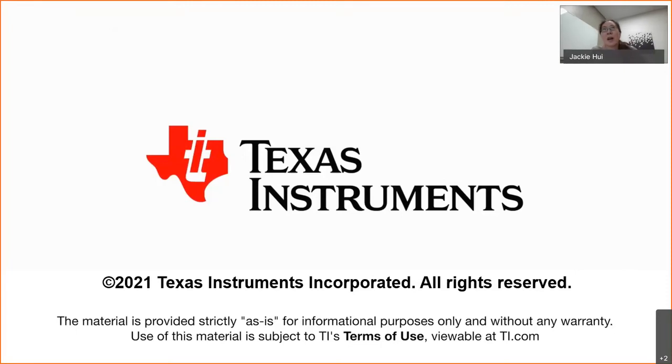Right, okay, thank you. For high voltage applications, we recommend trying to find a diode that has a maximum of 50 nanoseconds reverse recovery.